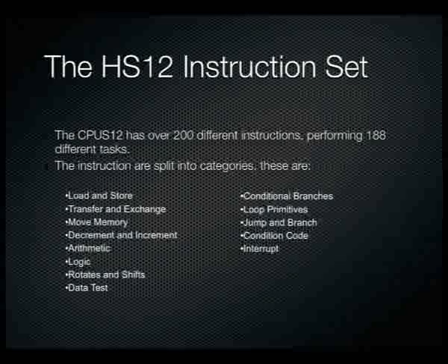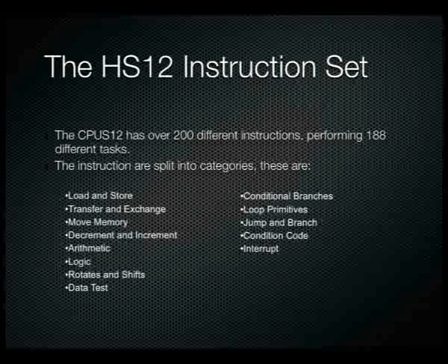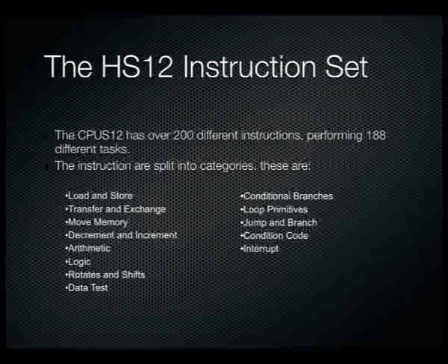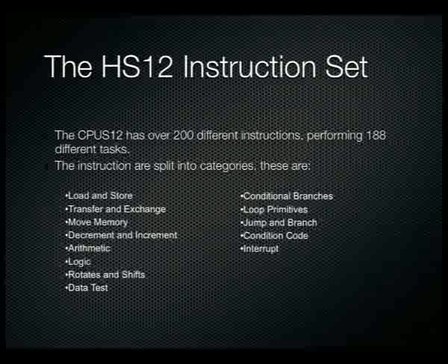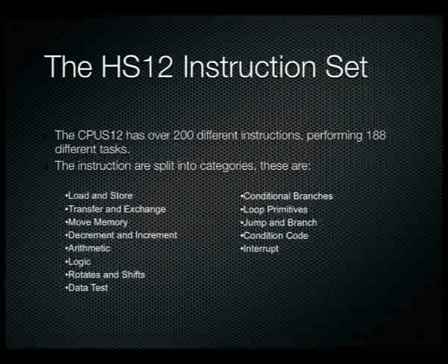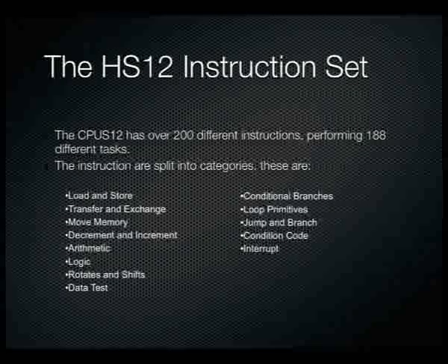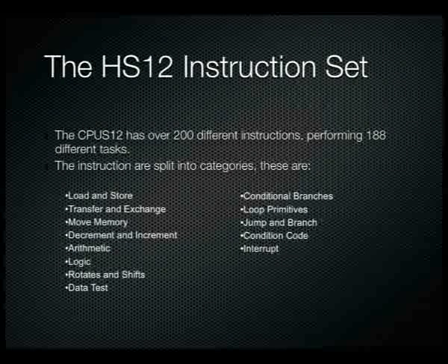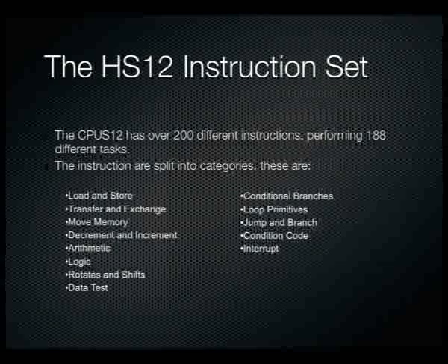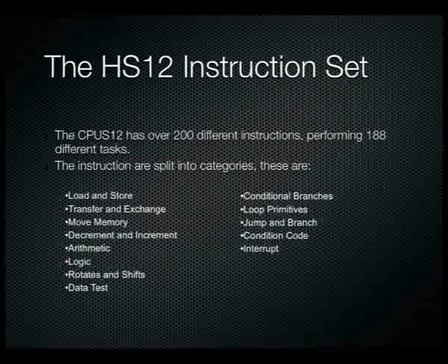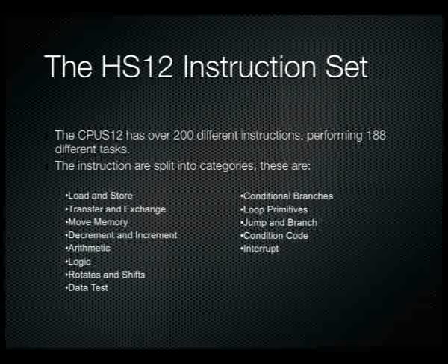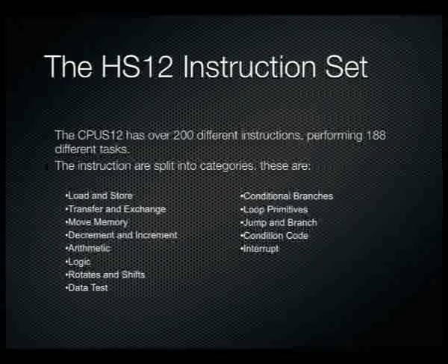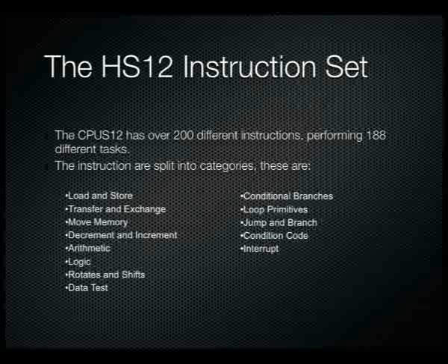When it comes to our instructions, as I said, they're split up into different categories. We have load and store instructions for getting data in and out of the processor. We have transfer and exchange instructions if we want to move data around within the processor. We have move instructions, so we can move in and out of memory. We can move bytes straight from one memory location to another without having to bring them inside the CPU. Obviously they're brought temporarily inside the CPU, but they're not stored anywhere inside our registers.